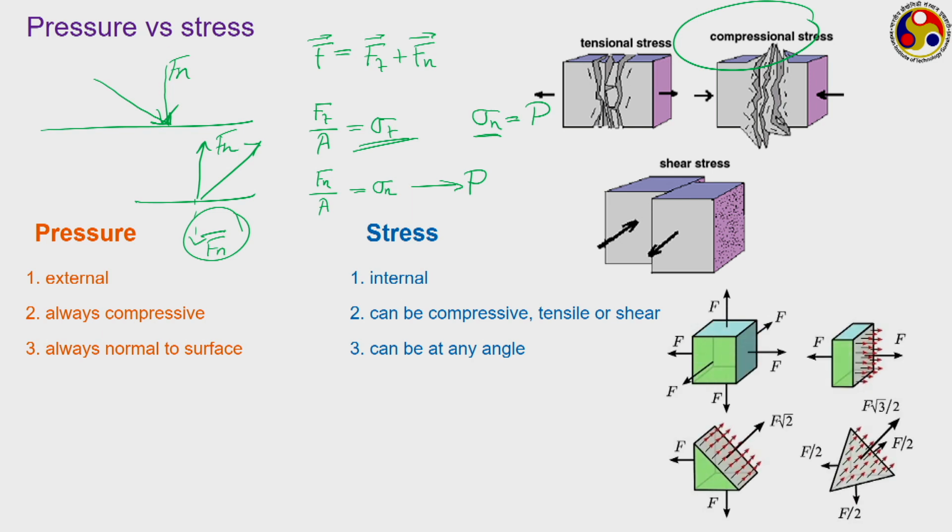Like we can see here, we are having a cube and forces acting parallel to each of them. Now, if we break them, in the second case also the surfaces are parallel to each other and the forces act normal to the surface. However, if we look at this particular case, here again the force is acting normal to the surface, but it is not in an orthogonal direction, because here we are talking about the surface which is not parallel to any of the orthogonal axes.